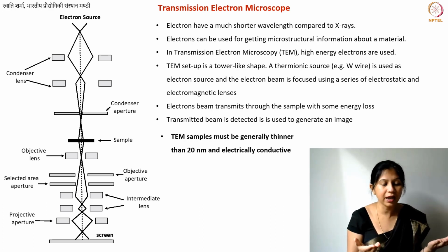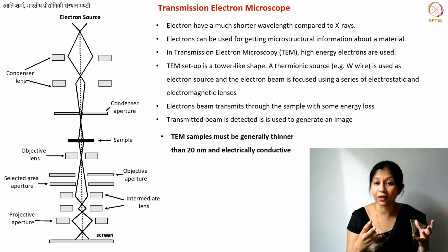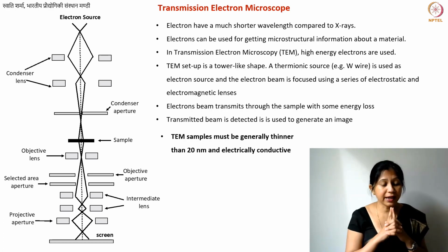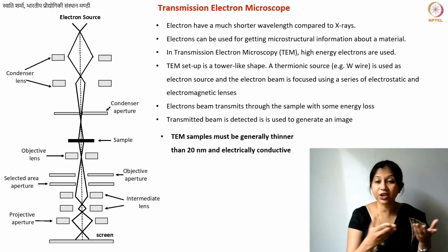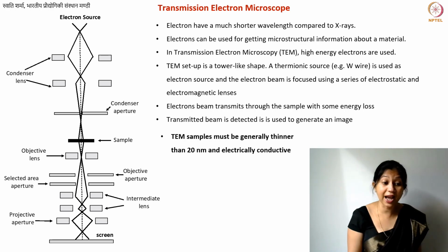You can definitely evaluate if the diameter of your tube, let's say, was 50 nanometer, or if you're using a carbon fiber. Often I see transmission electron micrographs of carbon fibers which are even 200 nanometer thick, or their diameter is 200 nanometer. In that case, you can measure the diameter of your fibers, but that you could even do using scanning electron microscopy, right?